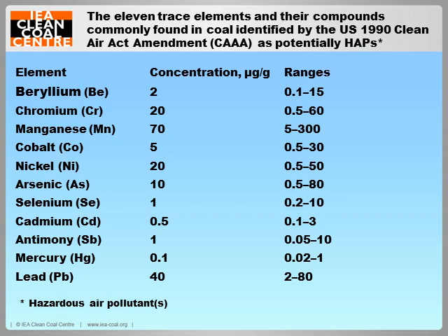In July 2012, amendments to the EPA rule were published, which included final limits for filterable particulate matter or total non-mercury hazardous air pollutant metals, or individual HAP metal limits for antimony, arsenic, beryllium, cadmium, chromium, cobalt, lead, manganese, nickel, and selenium. It is postulated that the MATS rule will require a minimum of 40% of all coal-fired power plants in the USA to deploy pollution control technologies to curb emissions of mercury and other air pollutants such as arsenic, chromium, nickel, and cyanide within 3 years.